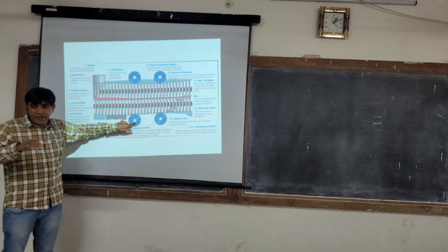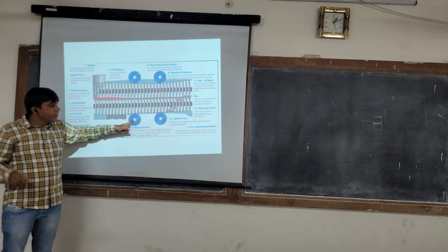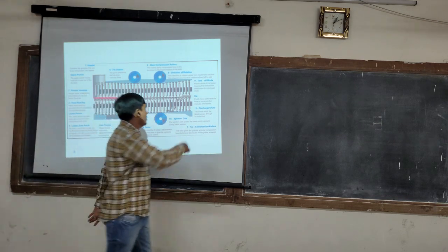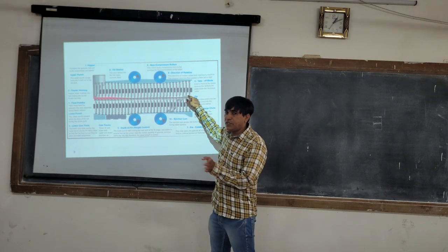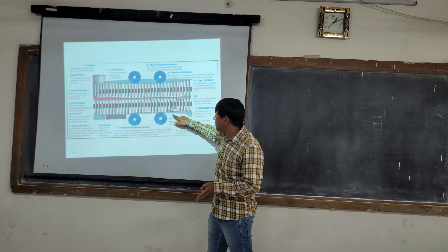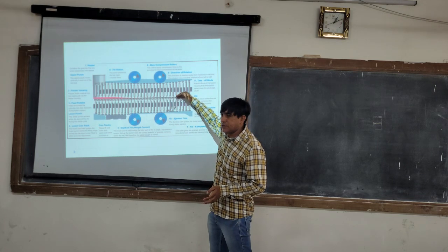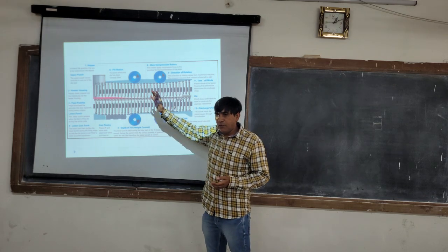So the mass will be compacted, the force will be taken away, and the air will escape from the pores. Then the tablet is finally compressed, and then it is ejected. One end of the feed frame will help in the ejection. Once the lower punch rises, it will move the tablet to the surface, and one end of the feed frame will scrape the tablet away.